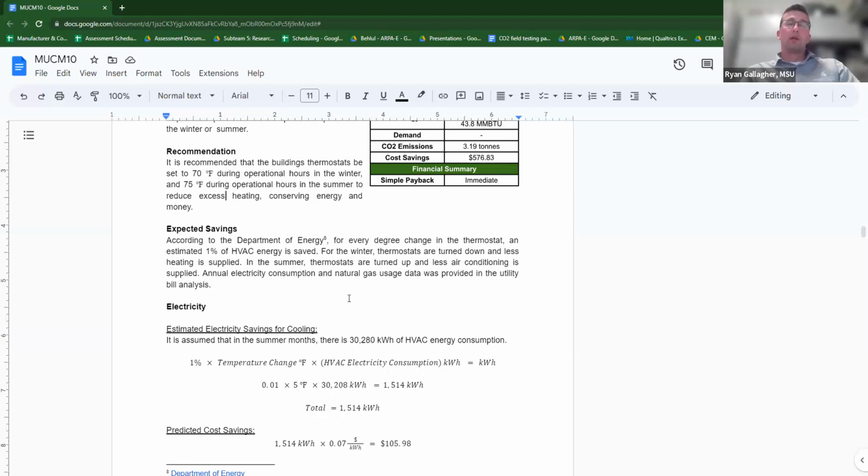In some areas, we can't do that. Like over at our football building, in some areas, we actually have limited cooling capacity. And so if the first 10 offices put their thermostats down to 70, the offices at the far end of the building will overheat because the others are taking all the cooling. So we end up having to lock those ones out and say everybody gets 75 because the people at the end would be like 80 or 85 degrees. So we run into all kinds of situations where we have to do different things, but for the most part, we give the users an operator range between 70 and 75 and lock them out virtually. Physically they can change the set point dial to whatever they want in their office, but we lock them out virtually through the software.